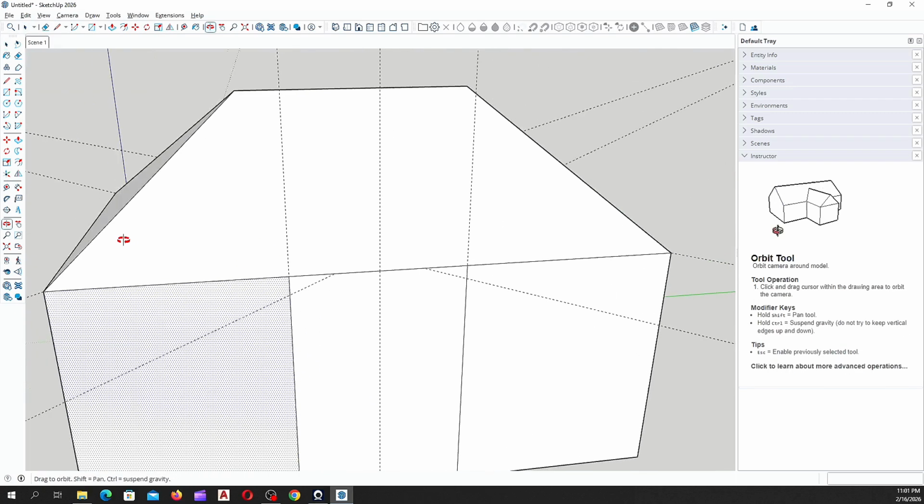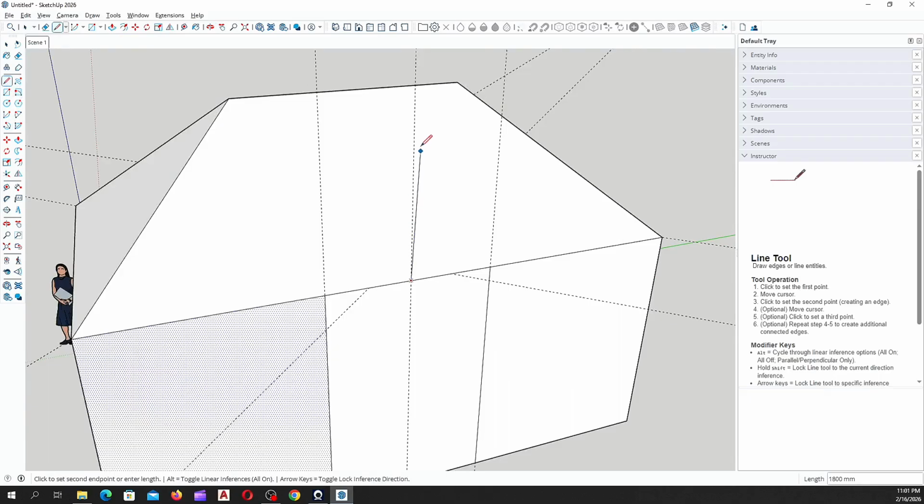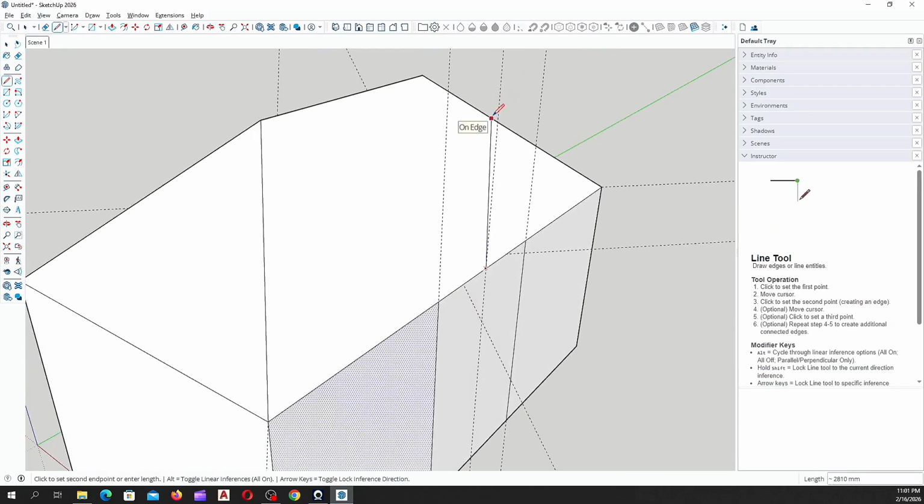Then one thing again I want us to do, from the center here, I'll pick a line. I'll lock the line by tapping my up arrow key. You see, we have this. Then I'll snap it to this edge. You see, provided I've locked it with my up arrow key on the blue axis, then I can snap to this edge. You see, it's still remaining. But once I deactivate my up arrow key, you see, the line is moving wheresoever direction I move to. But tapping your up arrow key, it locks it this way. Then coming to this point, you see, we have this.